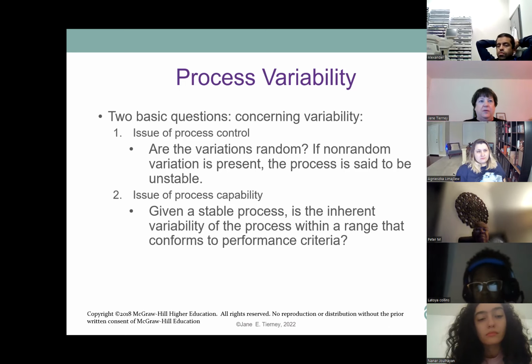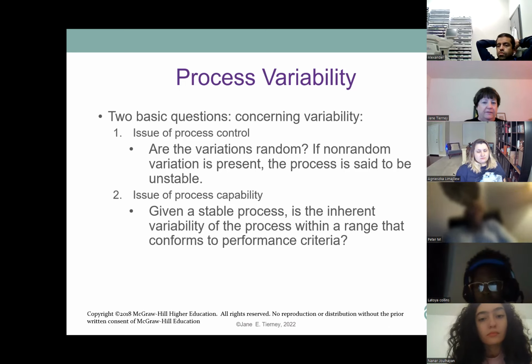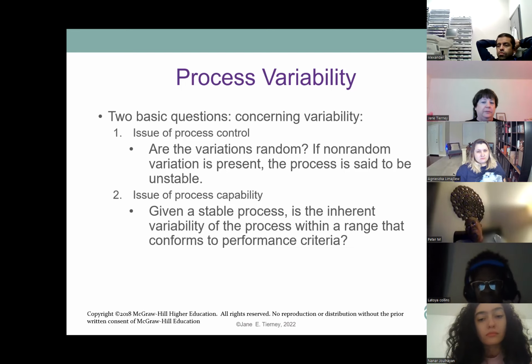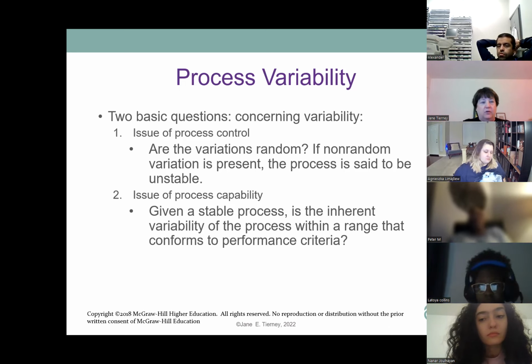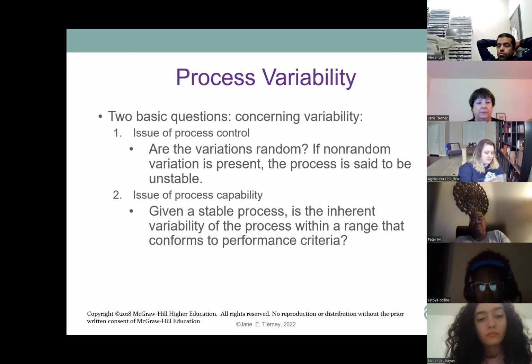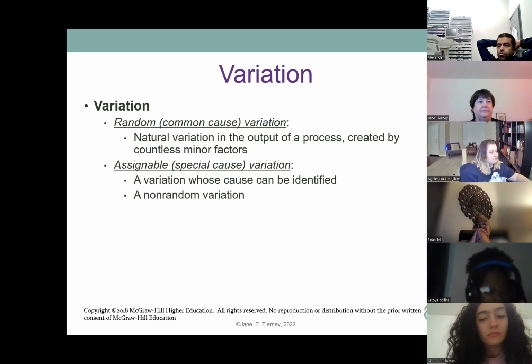If we have variation like that, it's probably going to be okay. If we have between, say, 5.5 and 6.5 inches, that's probably too much variation to say that we have a good foundation, because it's not going to be very level or very even, and that's going to cause problems down the road. So you have to determine that before you start your process.